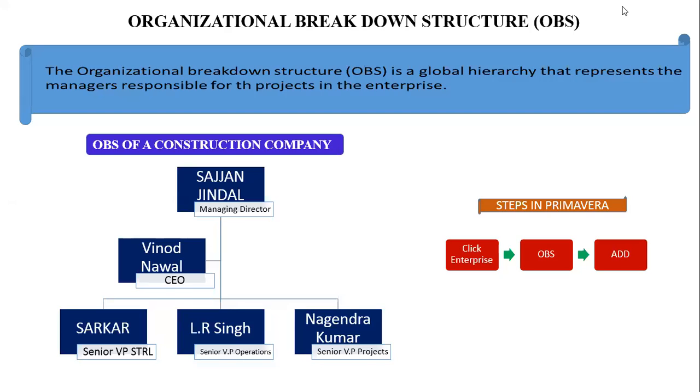Here we have the steps in Primavera. We need to click on enterprise, organization breakdown structure, and add. Just make a note of it. Steps in Primavera for OBS. Click on enterprise.